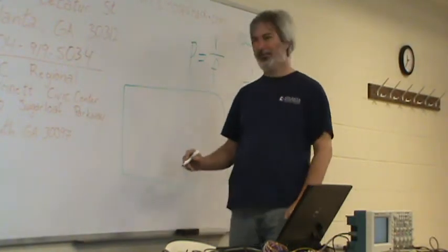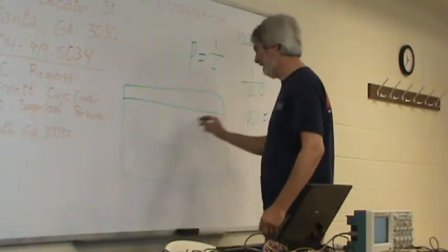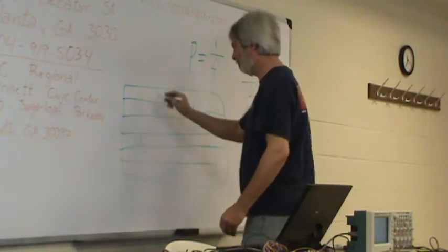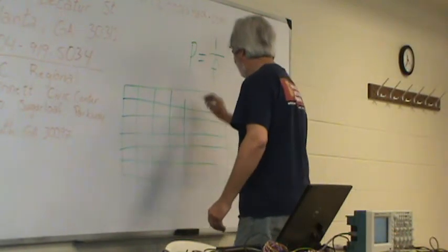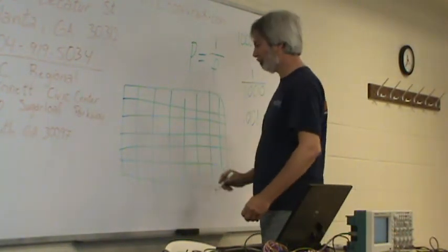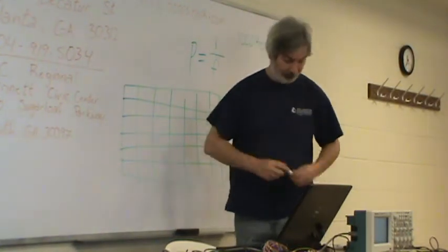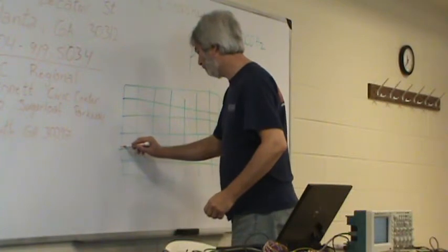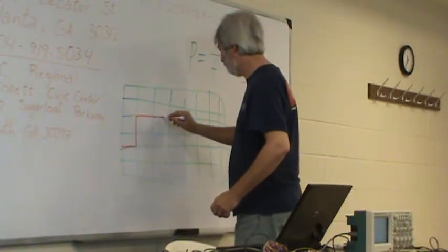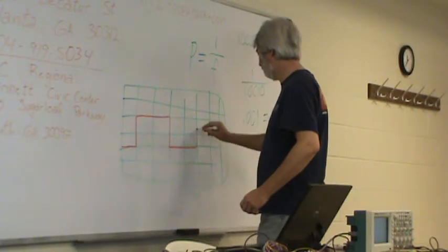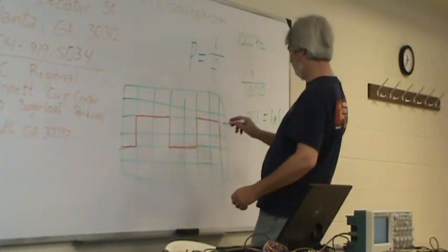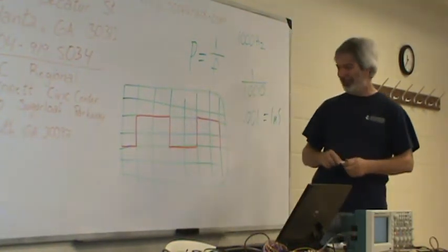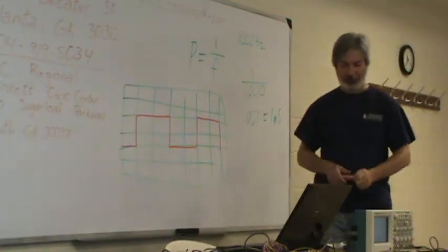There's a measurement button where you can choose what kind of information you want to display numerically. You can do things like peak voltage, amplitude voltage, frequency, period, on duty cycle, off duty cycle. That advanced scope there has all those kinds of abilities. You can usually hold up to 4 different variables on the side of the screen to show you different things that you can specify you want to see. Well, it's a color scope. Of course, now I gotta stand back here so you can actually see it.